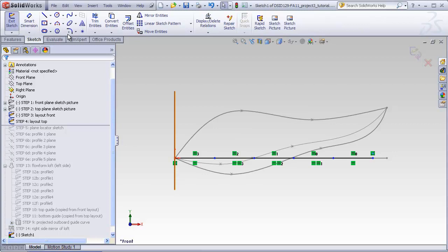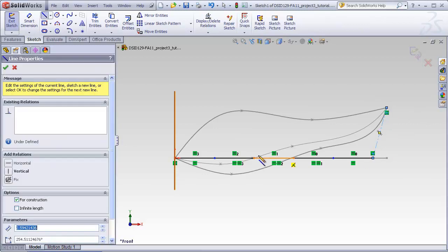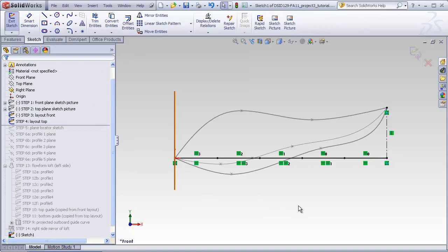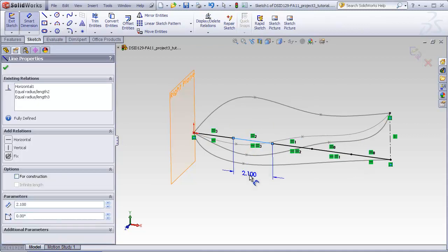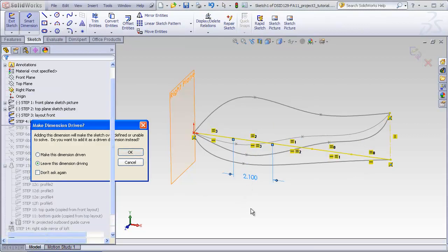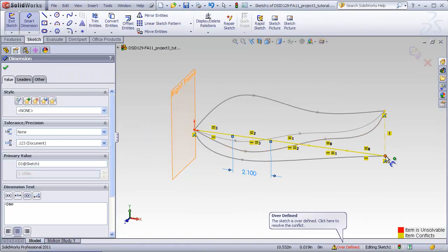and here I'll draw a vertical center line which aligns this last endpoint with the tail of my loft. Now what I have are 5 line segments, all the same length, and the endpoints between them are all evenly spaced. Since we know already this is 10 inches, these will be spaced at 2 inches apiece. Actually, I forgot that we had changed this to 10.5, so this is now 2.1 inches apiece.